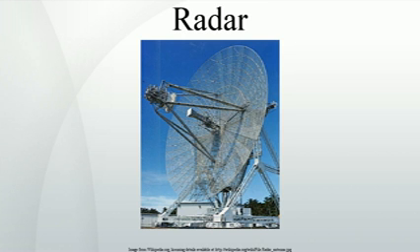Only the radial component of the speed is relevant. When the reflector is moving at right angle to the radar beam, it has no relative velocity. Vehicles and weather moving parallel to the radar beam produce the maximum Doppler frequency shift.